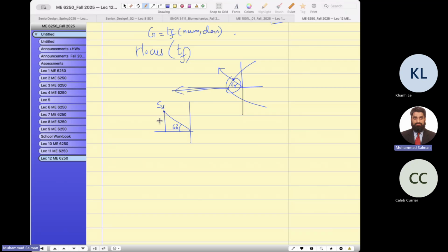So imagine, this is my j-axis. Can I write it like this, x and jy? Let's write y here. So can I write the desired pole location s as x plus jy, and then what is tangent 60 here? Y over x.